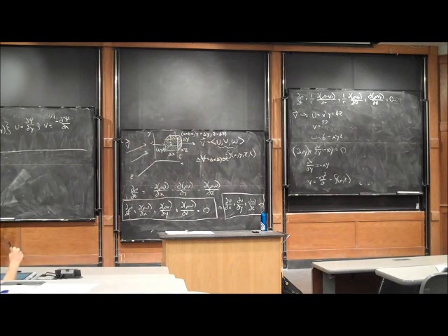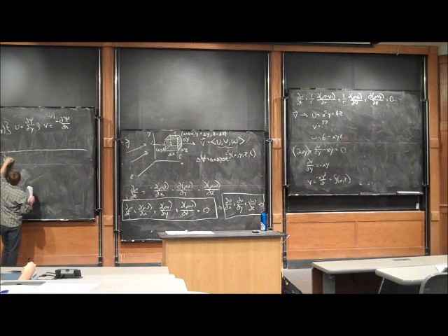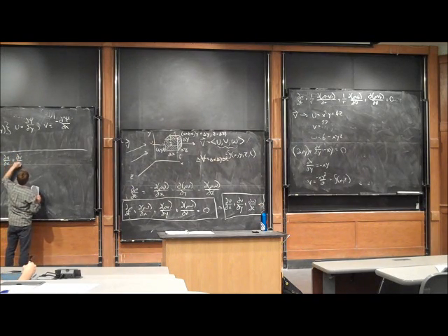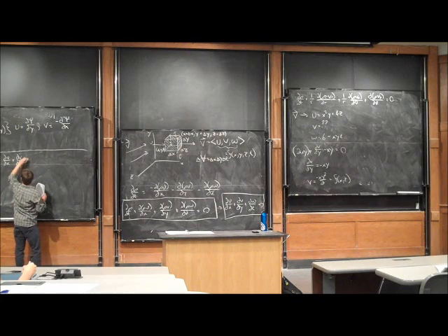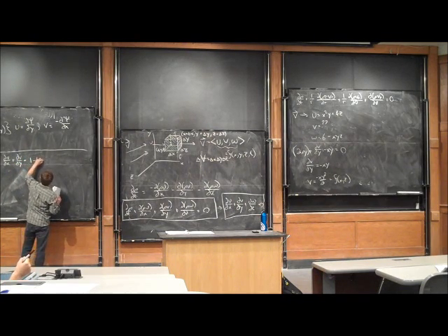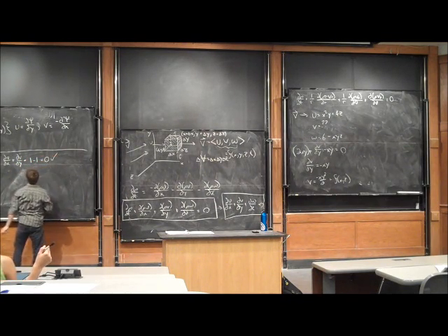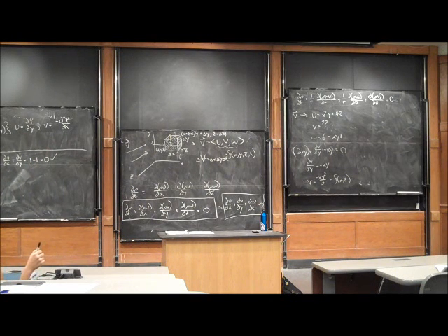Well, first let's make sure that we have a valid flow field. We need to make sure that this satisfies the conservation of mass. So du dx plus dv dy is equal to 1 minus 1, which is equal to 0. So this is a valid flow. This does not violate conservation of mass.